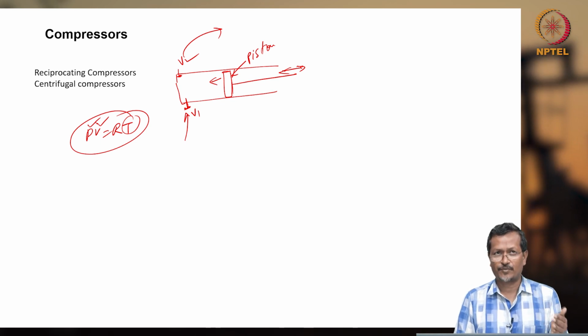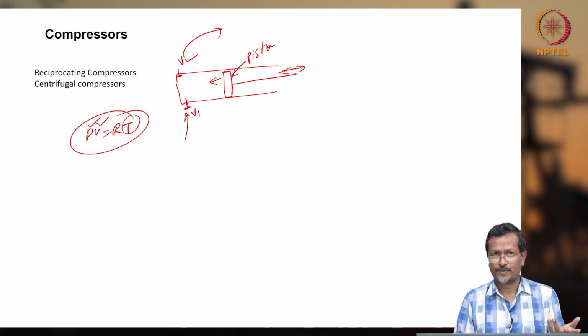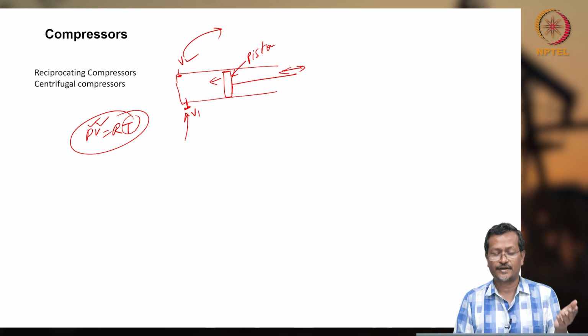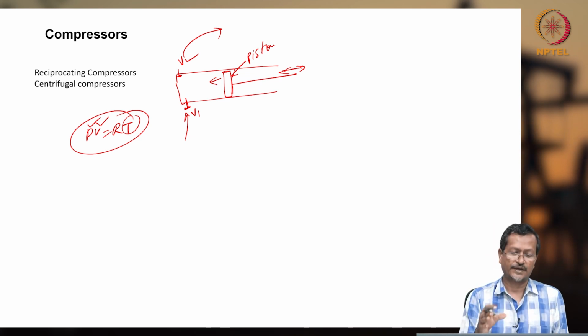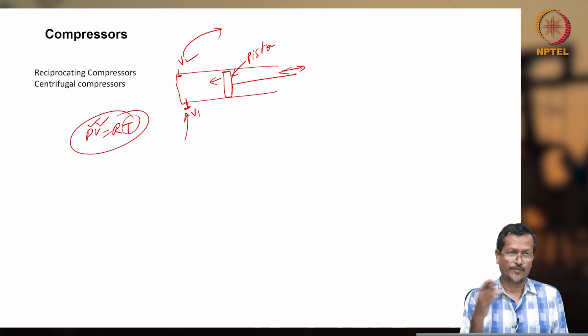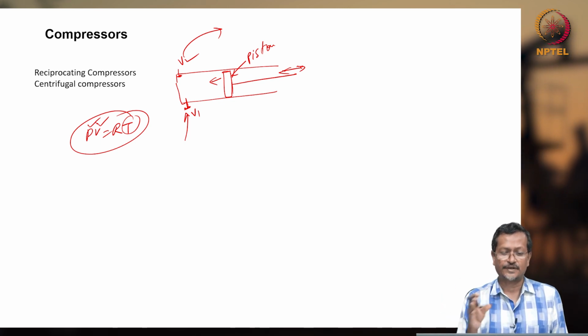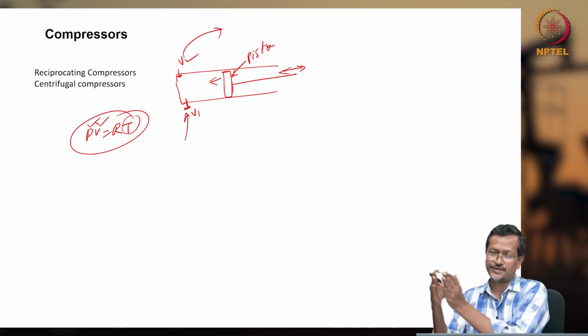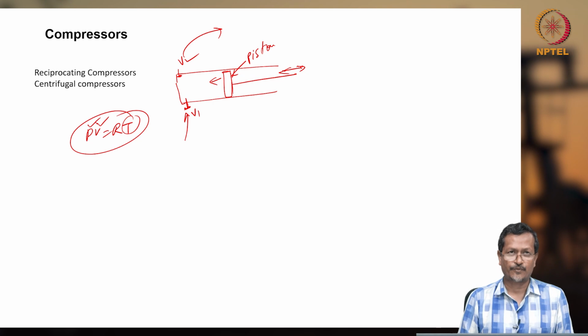If you want to use centrifugal compressors, it is like the centrifugal pump you have seen. In a similar way, with a centrifugal pump you are delivering liquid, but in this case you are delivering air or natural gas. So, you are compressing natural gas, and again the same phenomenon is there. When you are compressing at a very high rate, high temperature will be there, then you have to dissipate heat and compress it stage by stage, one by one, then you can get proper compression.